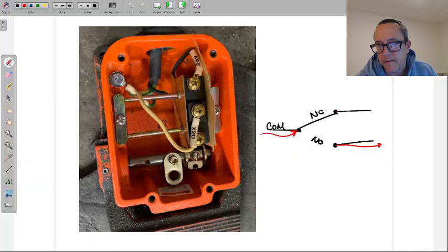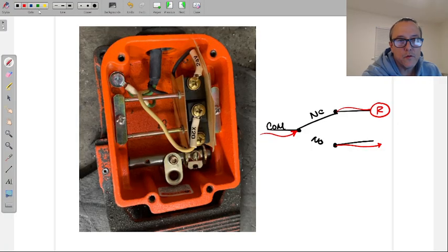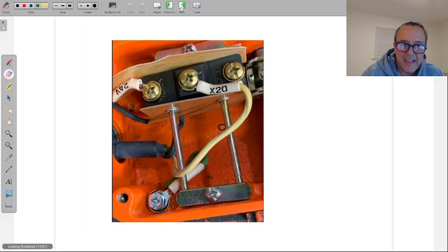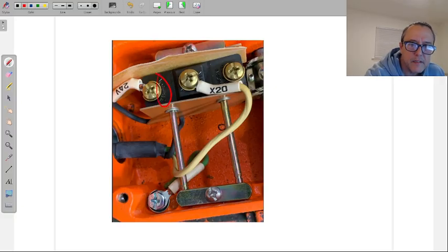Now again, you can also have, let's say for example, a red light attached to this, and then every time you press the foot pedal and energize the motor, it turns off the red light, and as soon as you let go of the foot pedal switch, it turns the red light back on. So however you want to use the 2 contact functions is fine. Sorry, I'm starting to get the itchy throat. And then here is just a better close-up of that, where you can't really see it too well there, but there it says common.